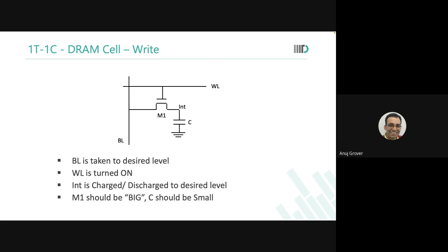And because of all these different reasons, we will go further and see that DRAMs are so slow, and you need to speed them up through different access protocols. You have DDR1, 2, 3, 4, 5, and all those things. So it's a fairly complex process to handle access through DRAMs. And just because of that, you have a coprocessor associated with DRAM access. So inside your DRAM chip itself there is a coprocessor, a small processor, which ensures that all these things are taken care of. All the protocols, everything is handled well.